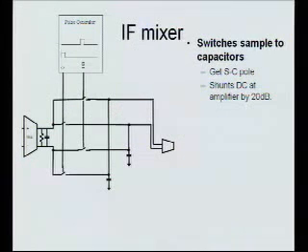All right, now we get to by far the most complicated circuit you'll ever see. So now I want to downconvert again from IF to baseband. And this is actually, we'll touch on why just putting an ADC here is hard. The problem is, at this point, I've had essentially one pole worth of filtering at the output of the mixer. So I've suppressed harmonics of the IF by one pole's worth, so not very much.